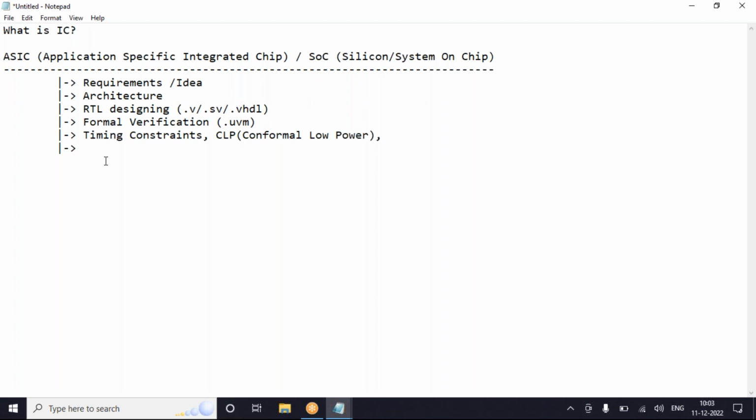Now, what we need to do is testing. For that particular testing, there are two ways. First is, with respect to the chip, or let's say whenever you write a code, with respect to that code, you are doing the formal verification by using test bench vectors. Right? Now, once I have designed that particular chip, I'm going to be using the same test bench vectors only.